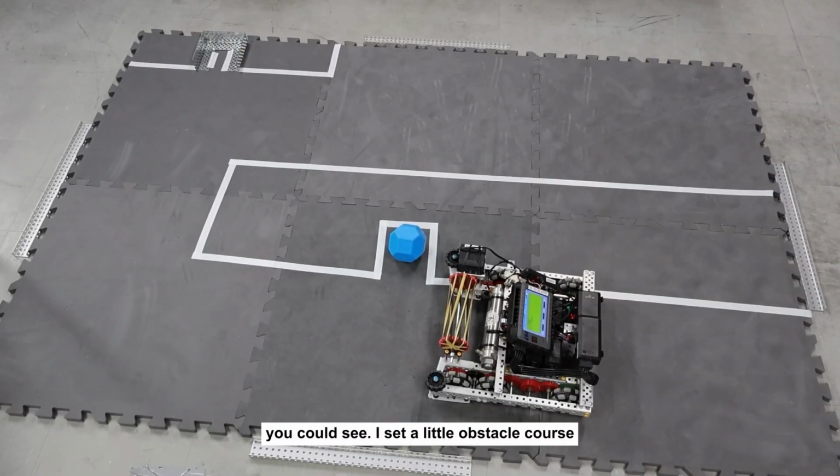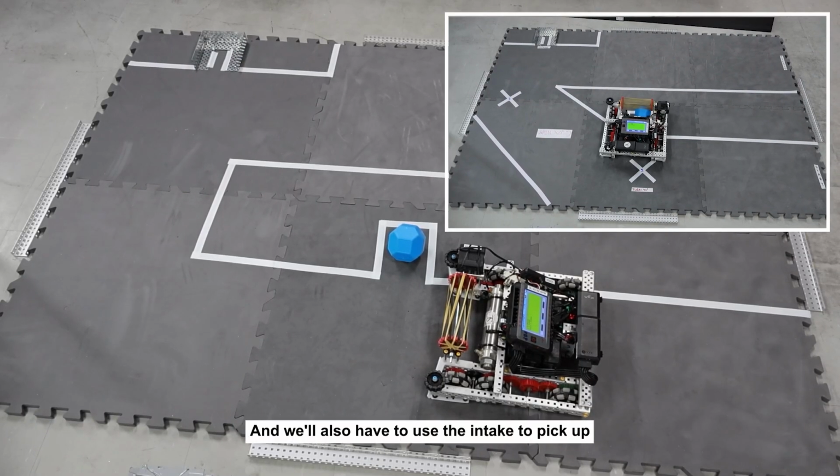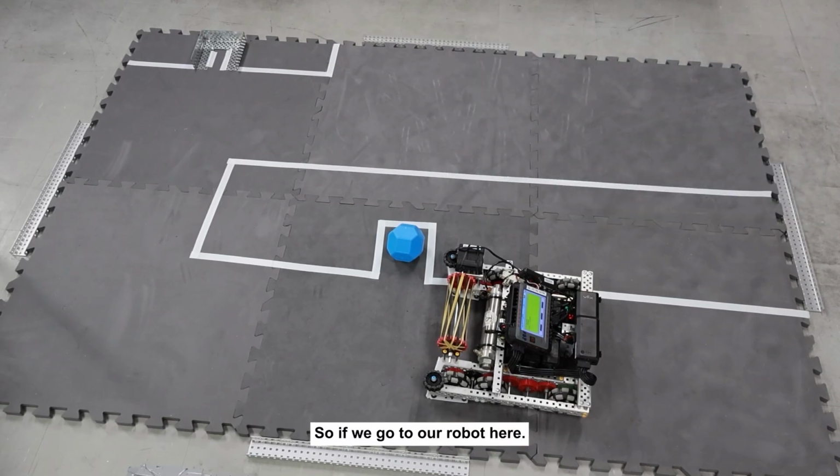You can see I've set up a little obstacle course for the robot to complete. This will take rotational moves, linear moves, and we'll also have to use the intake to pick up and put down the ball as well. First, I'll tell you how to do the linear moves. We're actually going to use the coordinates on the screen to program it, so we know where it needs to go because it's an exact coordinate.